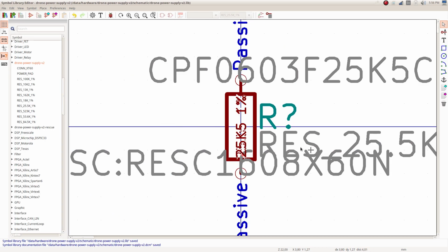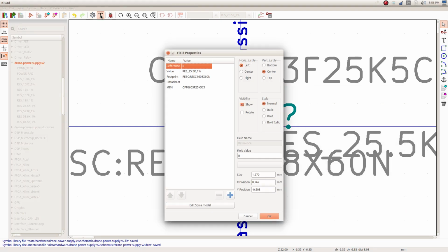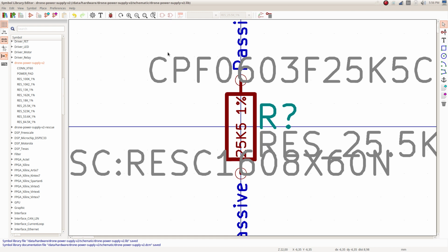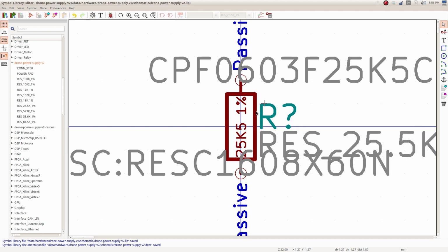Did I forget anything, by the way? Did I forget anything on this component? I don't think so. I'm gonna find out later. When I do the BOM and then I go through all of the manufacturer numbers, I may actually notice that I made some mistake and just copy-pasted a wrong manufacturer number. But that's a separate step, and that step is something that you always have to do anyway in the end. But luckily, if you work like this, you only have to do that step once. So once you have validated your components and you know that they're correct and you know that the footprints are correct, then you never have to do that again, which is very nice.